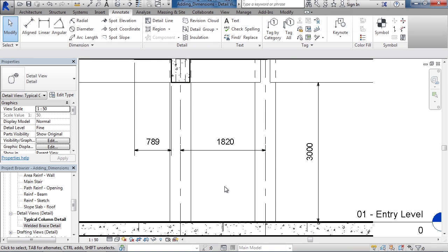So as a review, in this lesson, we looked at adding dimensions. We used the Align dimension to create a linear dimension between two surfaces, or two entities we selected. We also selected multiple entities to create additional dimensions and align them with previous dimensions. Lastly, we selected a dimension to modify the dimension, where we can move the dimension text, move the arrows of the dimension, and if you double-click the dimension text, you can update the dimension text itself.